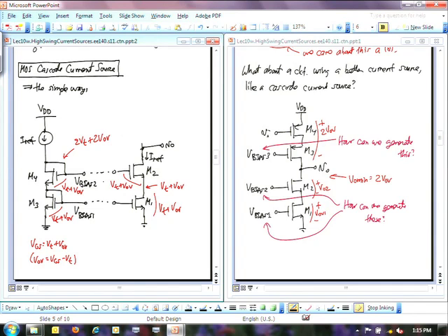So that voltage is VT plus VOV, and so in the end, I can take this only down to VOV across M2, because if the drain to source voltage of M2 drops below VOV, it becomes triode, and my gain suddenly disappears. And so that means V output min is going to be equal to a VT plus 2 VOV. Okay, that is a problem, because that's 1 VT higher than it has to be. So we don't like this at all.